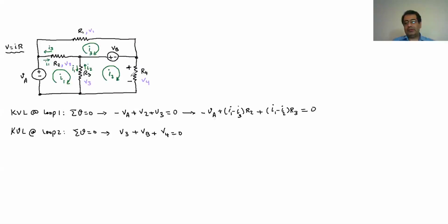In the simple format, when you do the mesh current, just add all the voltage in the resistance. It's an easier way of doing that. Add all the voltage in the resistance, and don't worry about the sign. Only look after the sign for the voltage in the battery. So if you hit the positive, put the positive. If you hit the negative, put the negative first.